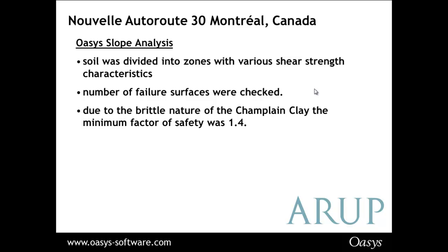Now, Slope was used extensively on this. It was used to design the embankment material, and it was used for the earthquake formation. So for this particular analysis, Slope was divided into zones with various shear strength characteristics. A number of failure surfaces were checked,